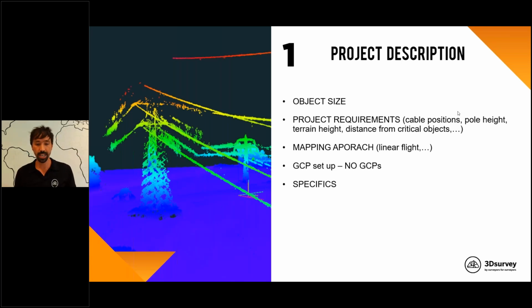And the second option is the approach. We suggest you turn the camera gimbal a bit to the front. I used a 60-degree camera gimbal and got really good results out of it. This helps you increase the overlap between images, because if the camera is pointing in front, we get more area in the same image, a longer cable section is on the image, and it's easier to reconstruct the points later.